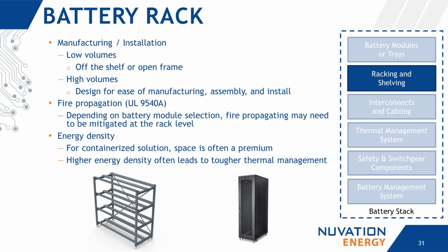For battery stacks that are part of a UL 9540 system, then fire propagation testing, which is UL 9540A, is something to take note of. Depending on the battery module selection, if not contained within the module, fire propagation may need to be mitigated at the rack level. In this case, fire barriers or metal sidewalls may be required.